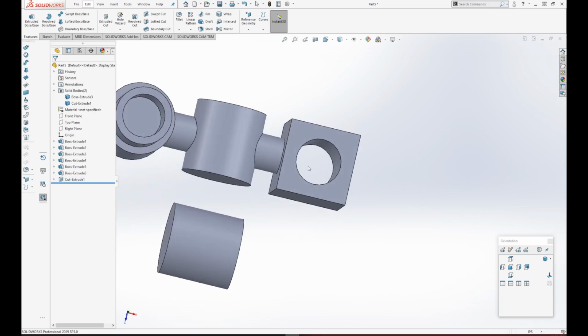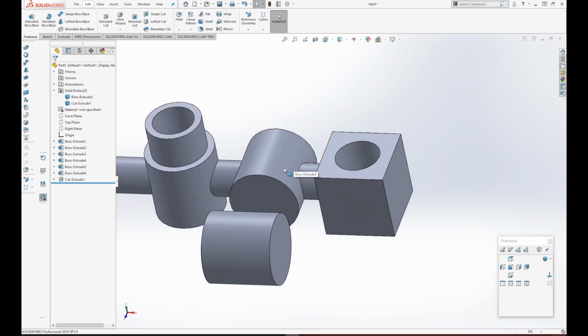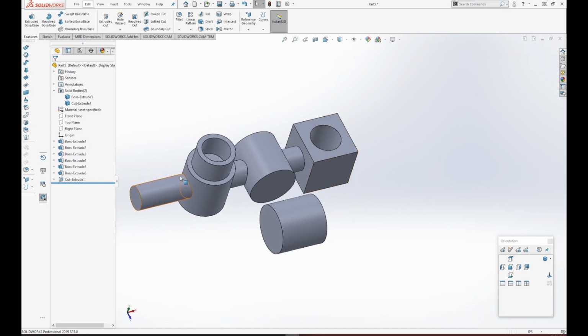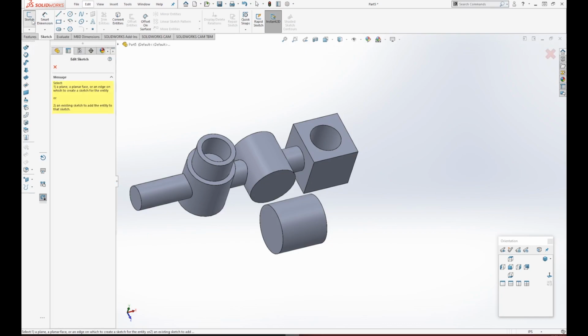So if you guys have noticed by now, I'm showing you very basic, simple stuff. We're going slow, guys. I could have really zipped through showing you the extrude base boss and the extrude cut, but I wanted to show you those very minor intricacies about selecting the little merge results checkbox if you want whatever you built on top of another part to connect with it or not. And in order to select which parts you want to connect to it, you uncheck that auto. Just little stuff like that. You need to know this stuff when you're building in SolidWorks or it's just not going to turn out the way that you want it to. So we're going slow, guys, and I just wanted to really show you that carefully. Okay, let's go into our sketch mode.